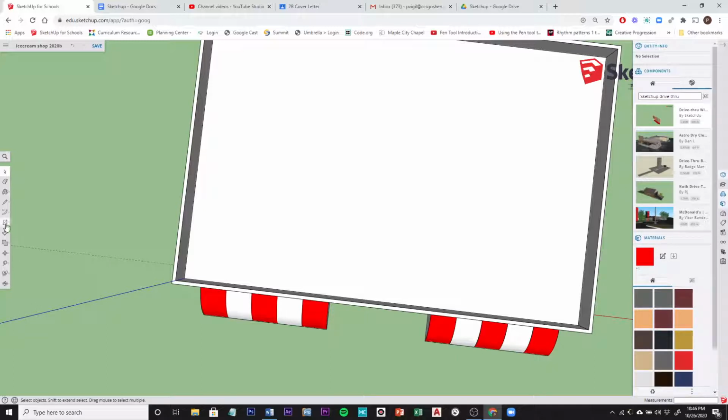And I'm going to make a rectangle. So I'm going to go to the rectangle tool. And I want to make sure that I'm going to be drawing on this face. So once I get that screen tip that says on face, I'm going to hold the shift key down to make sure I stay on that face. And while I'm holding that shift key down, I'm going to click in this corner at the end point. Now I can release the shift key because I'm on the right face and I've clicked my starting point. I'm just going to drag away in this direction. And then I'm going to type in 30 and then apostrophe, so 30 feet, and then a comma, 2 feet. So a 30 by 2 foot rectangle is what we're making. Press enter. Just make sure that your rectangle looks like this. So that, again, that's 30 feet by 2 feet.